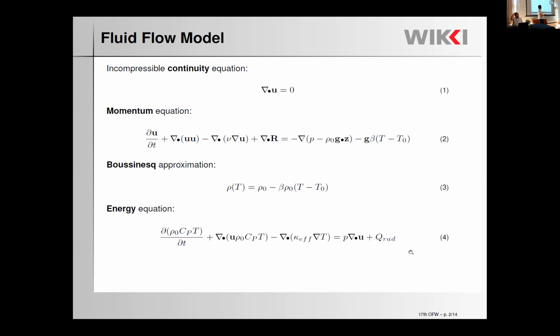Okay. So let's just jump right into it. Let's start with the fluid flow model. It's quite a simple model, it should be quite familiar to everybody here. It's just Reynolds-averaged Navier-Stokes equations. We have a continuity equation which in incompressible form takes the simple form of just divergence being 0. There is also a momentum equation, pretty much familiar terms to everyone here. We have the temporal derivative term, the convection, diffusion, and the forces on the right side.